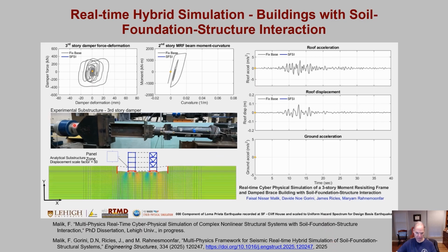Now here is the damper. This damper is at the upper floor, and the other dampers are modeled numerically. What I'm going to do here is a replay for the soil foundation structure interaction cases. This will be where the curve is going to evolve with a blue color in these plots. And the replay is going to recover at the interface neural network forces and displacements, which I'll then feed into my finite element model in the post-hybrid simulation just to observe locally the deformations and the strains and stresses in the soil. So this allows me to recover. It's actually interpretable. So with that, let's go ahead and play this.